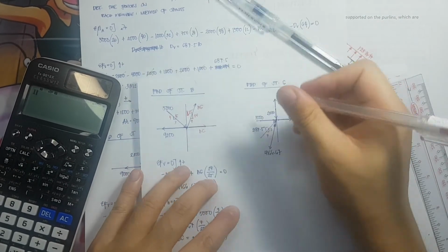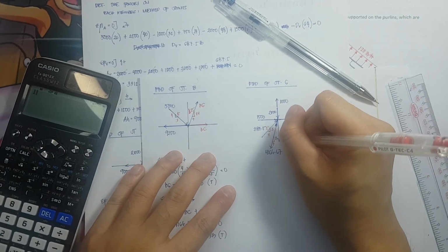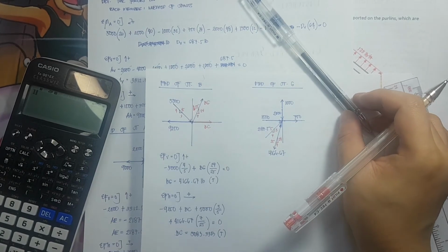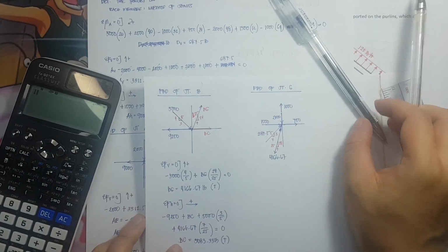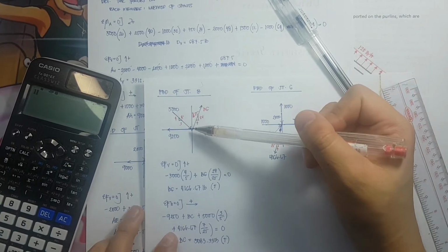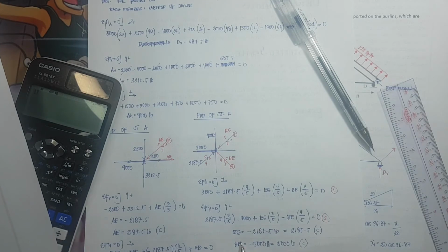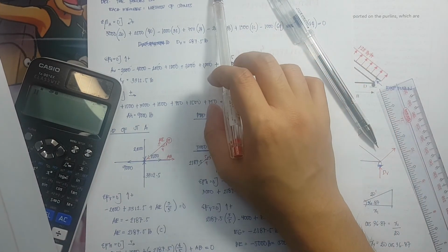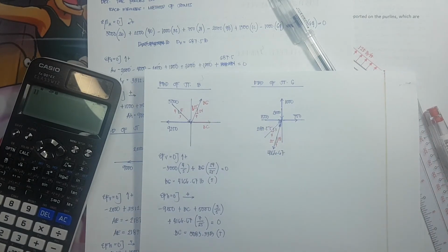The slope here is 7 horizontal, 24 vertical, and the hypotenuse of 25. Okay, so are we sure here with our BG? So what member is this? 5,000. So BE is compression. So that is downward force.